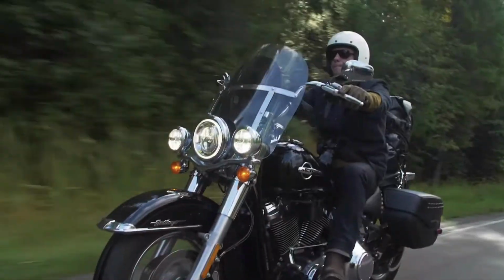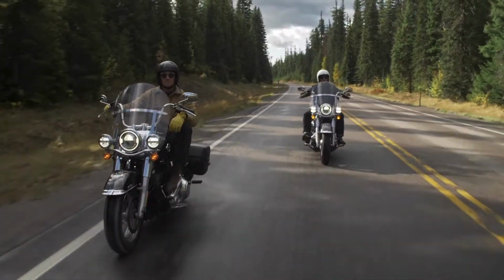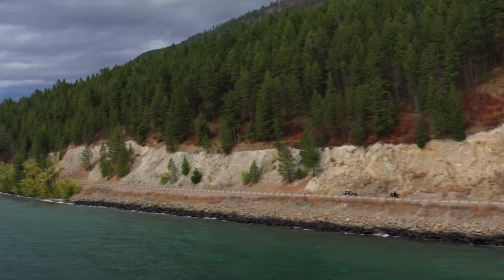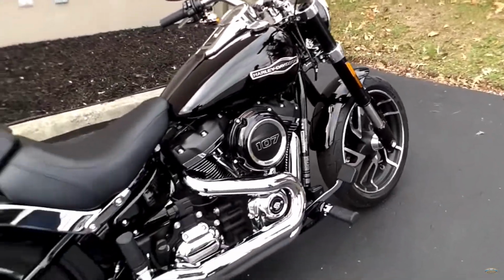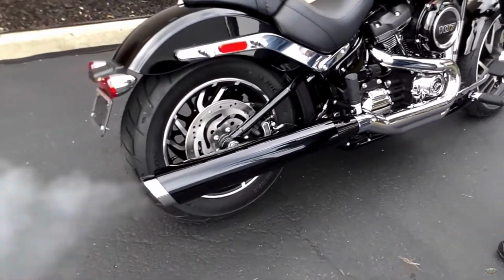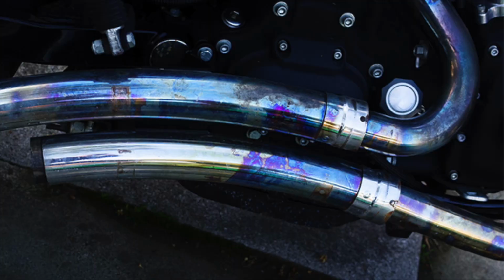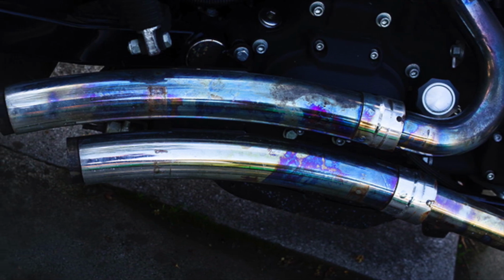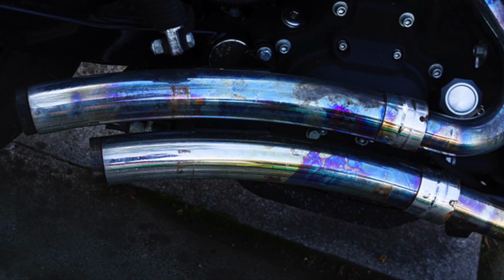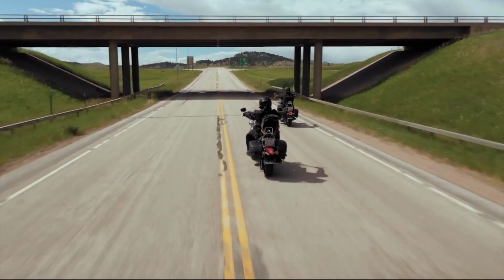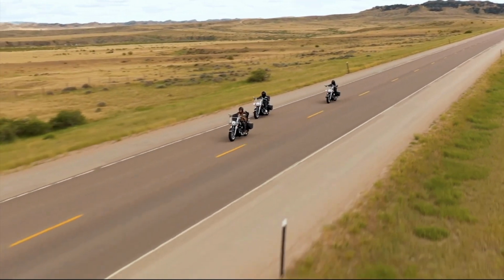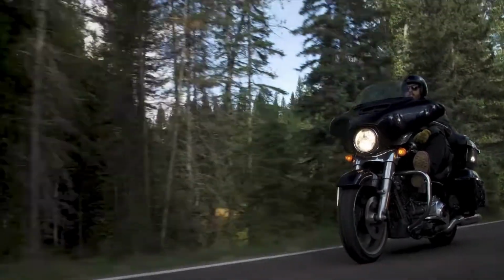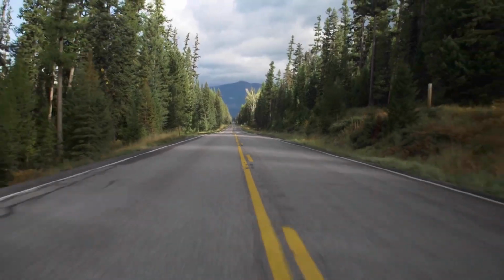Long-term engine operation with a lean mixture causes slowdown in combustion speed of the mixture and increases temperature in the combustion chamber. Combustion of the mixture continues into the exhaust cycle around the valves and into the exhaust manifold. Temperature in the combustion chamber rises. The running of the engine is often unstable and there is a risk of damaging the valves and overheating the exhaust manifold. Combustion of a slightly rich mixture increases engine torque and reduces the temperature in the combustion chamber. At the same time, however, the engine's fuel consumption increases.